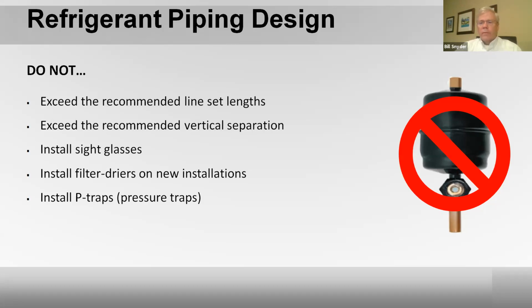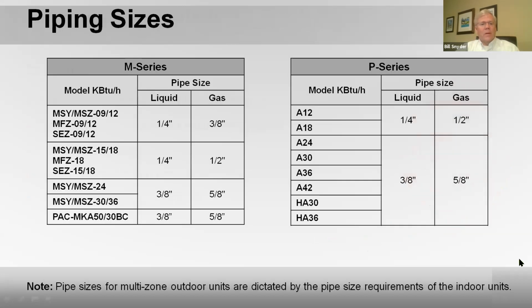Don't install P-traps. We never do that because that's a pressure trap, and that will get oil. It'll become an oil trap. It'll end up full of oil, and when our systems ramp up to full speed, it'll suck that oil out, and you'll get liquid oil hitting the compressor as a slug, and that would not be good.